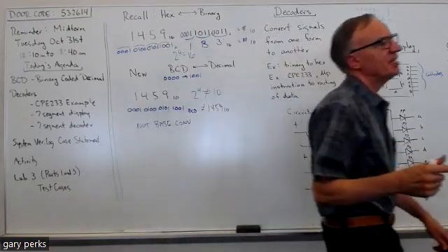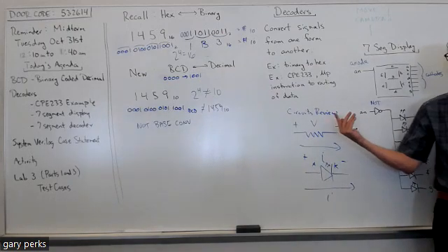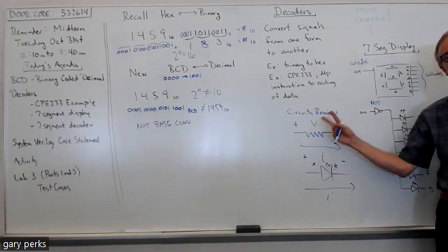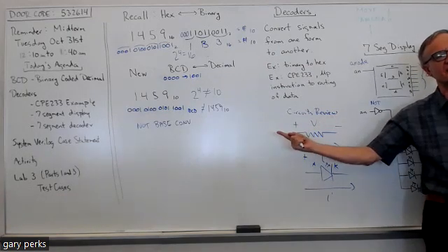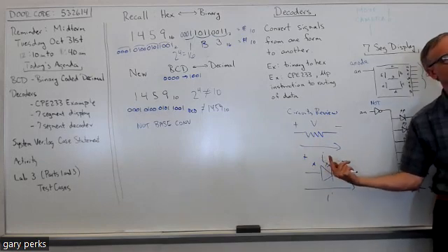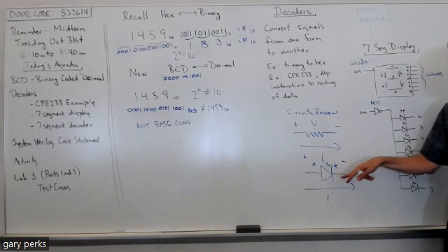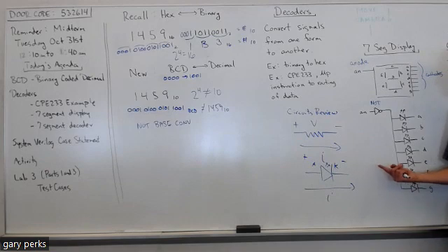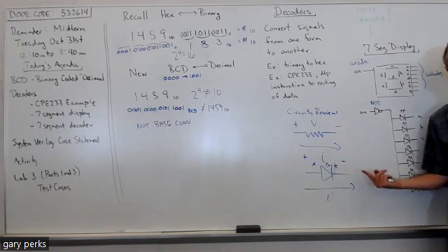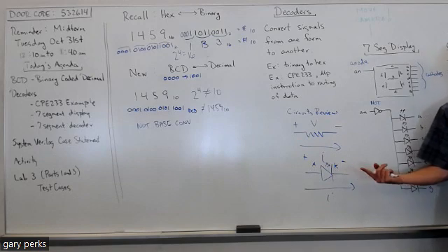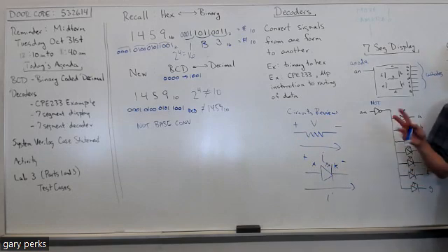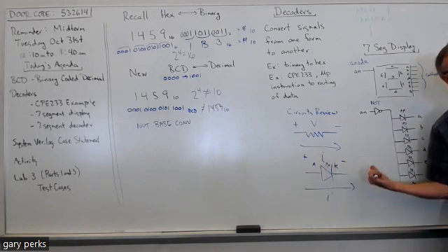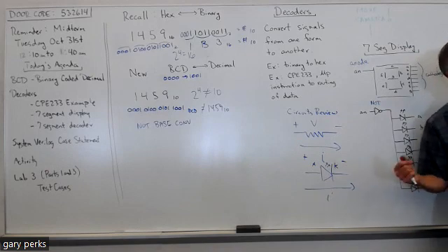And the other thing about diodes, and this is the difference between a diode and a resistor, is that with a resistor, if I reverse the polarity of the voltage, the current's going to flow the other way. But with a diode, if I put the higher voltage on the cathode and the lower voltage on the anode, the way diodes are constructed, they won't allow current to flow cathode to anode. Ideally, you'd have zero current. You probably heard forward bias, reverse bias. This is forward bias when current's flowing anode to cathode. Reverse bias is the opposite, ideally no current.